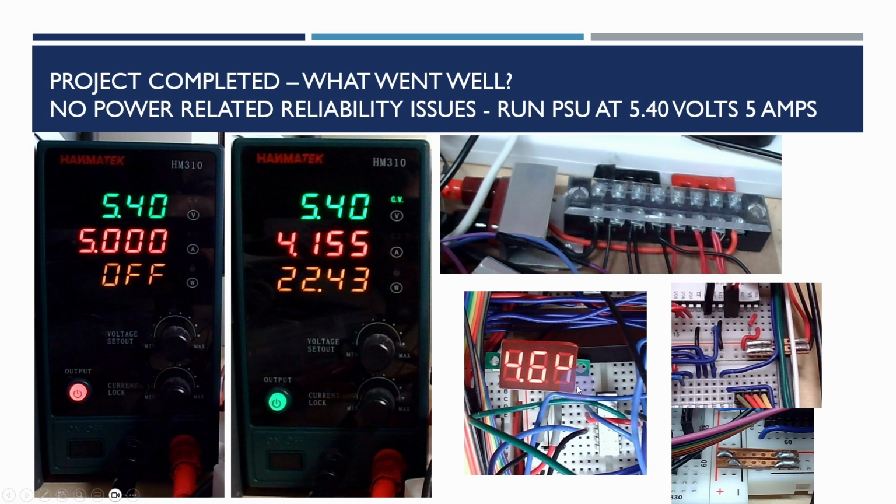There were some of the early projects I did on the 6809. My video card had about 3.6 volts in one corner, so that was definitely causing problems. So I'd recommend trying to get these type of little power meters. They are £1 each from my local supplier, Bitsbox, I use in the UK, and they're definitely worthwhile putting in certain locations around the board so you can spot power problems before they bite you.